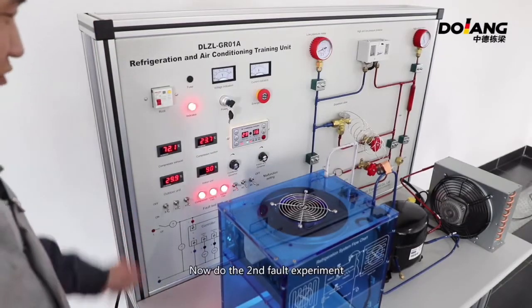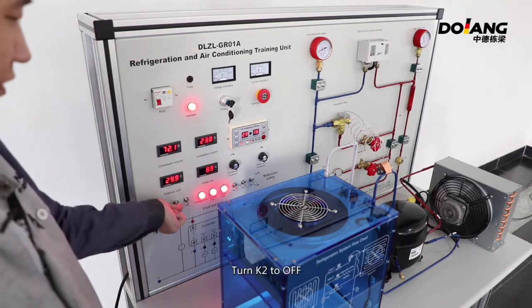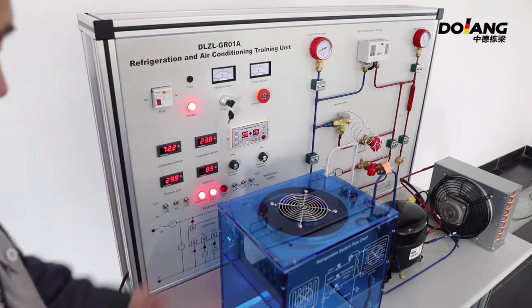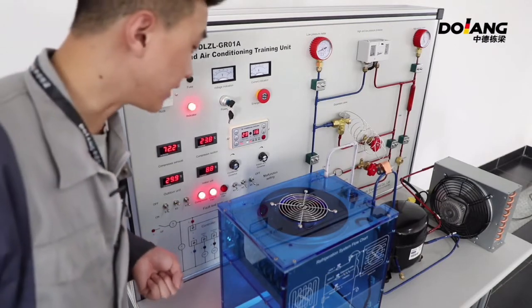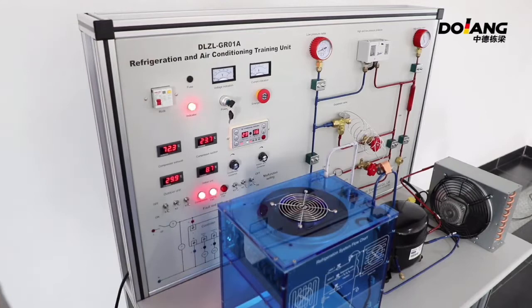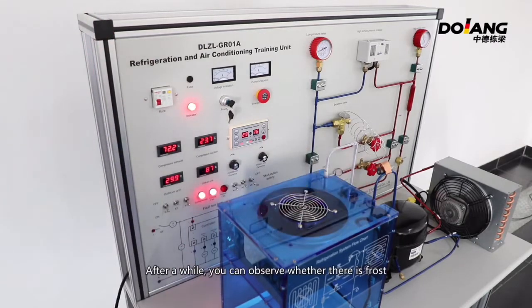Now do the second fault experiment. Turn K2 to off. Now the simulated indoor indicator is on. The simulated indoor evaporator fan does not run. After a while, you can observe whether there is frost.